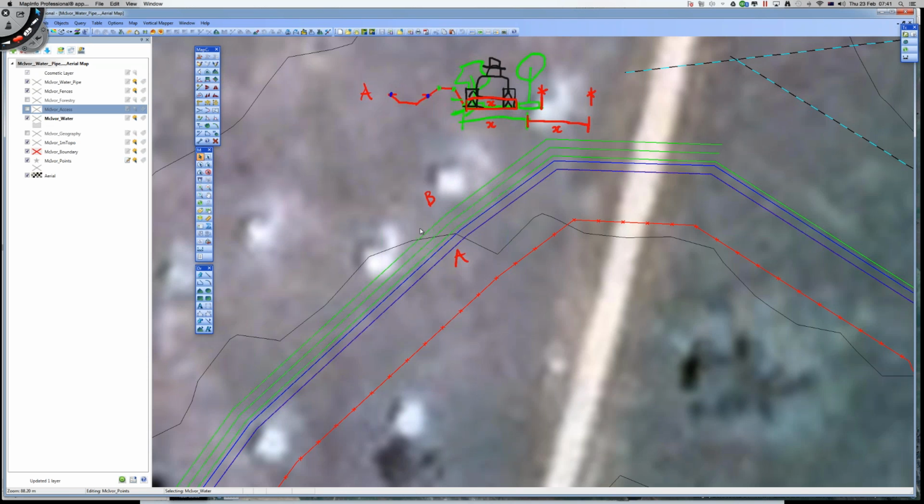So, or ditches and banks. If you go back to the ditch, for example, you will do some work on calculating the peak flow volumes running off that catchment using your hydrologic soil groups data and your surface area data, and then start to work out how wide that embankment, that ditch might need to be. The ditch might change in its size over the length of it, and that's something to consider. A lot of people, just for ease of construction, will just make the ditch the same dimension the whole way along, right?